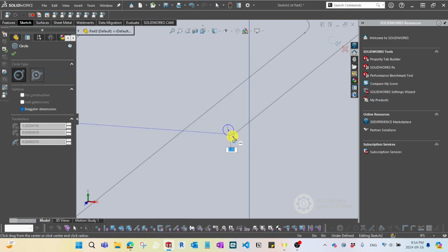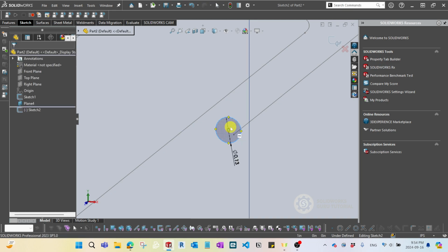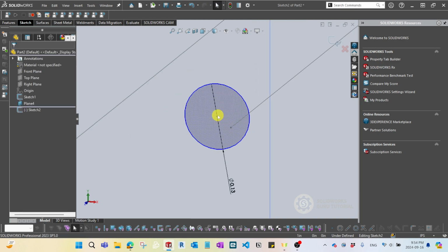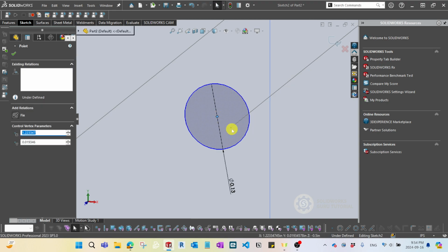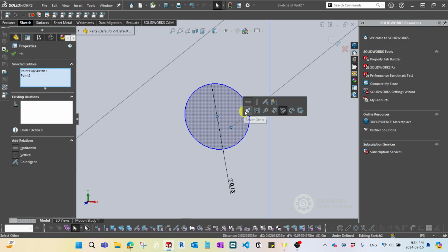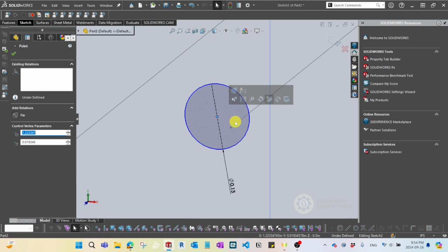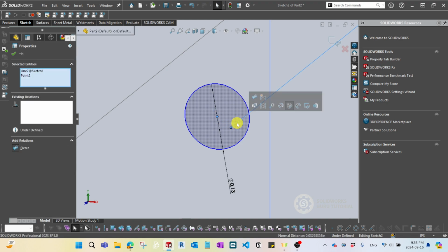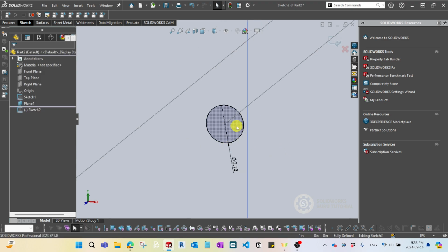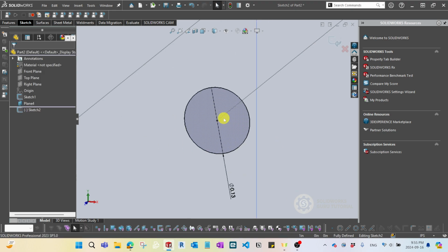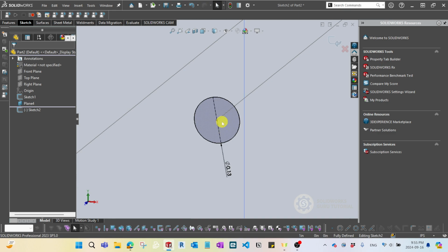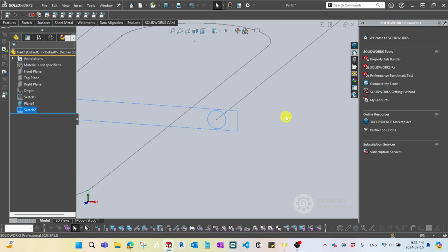And then I'm just gonna assign 0.125 inches, okay? And then what I want you to do is click this center point and then click this point. This is also one way, but I want you to also click this point, and then select this path. And then there's a make pierce, okay? That's gonna pierce to the path line, so that's gonna do the same thing, okay? So I'm just gonna escape.